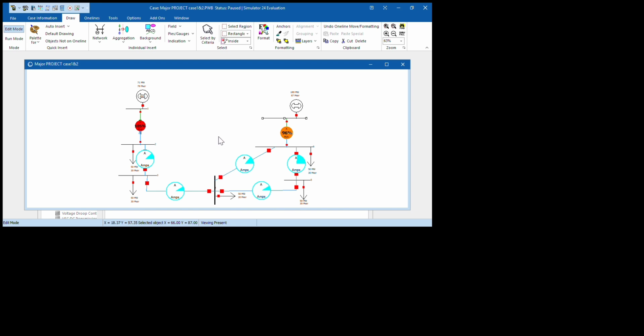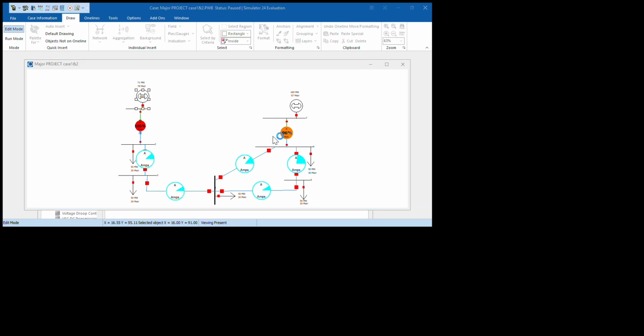So for generator 1, as shown here, we need to include the fault parameters for the generator also, which are the positive, negative, and zero sequence impedance, as shown here, which is given in the question. So we just take the same parameters because the base is the same, so it's not changing. But for generator 2, the fault parameter values are half of those given in the question because of the base ratio. The new base over old base is equal to 1/2.